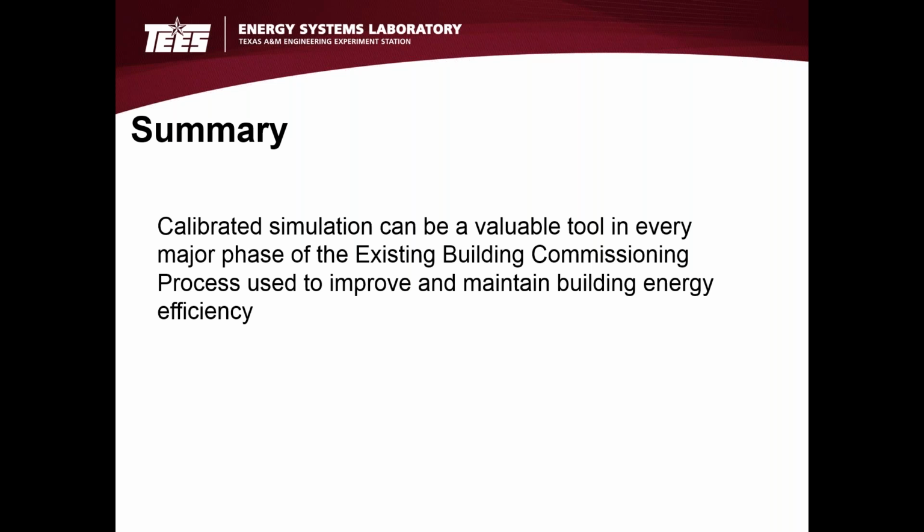And of course, I can think back to experiences of seeing construction details where people said that something was insulated, and you'd put an IR thermography gun on a building and you could see it wasn't insulated, or maybe there were big holes in the insulation, things like that.